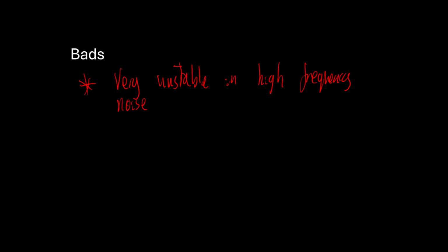So if it's high frequency noise, that's a high rate of change of the error, which means KD is amplifying that and reacting way too strongly to it. So this typically causes jittering, oscillations, and other problems. And it's not good for systems with high frequency noise.